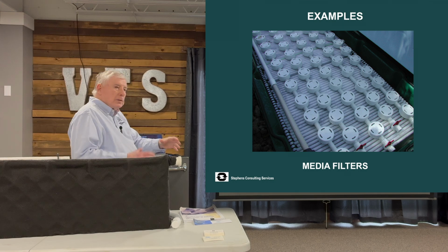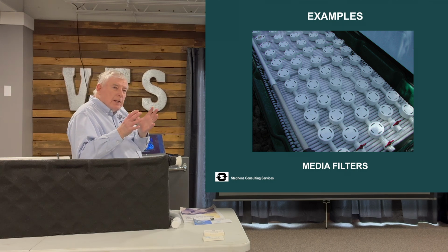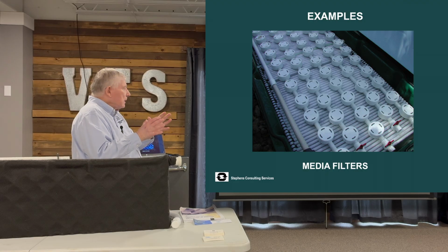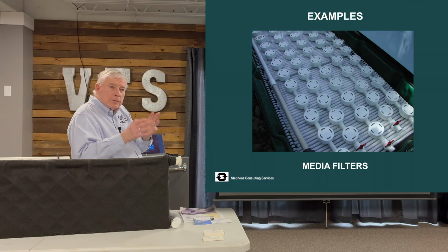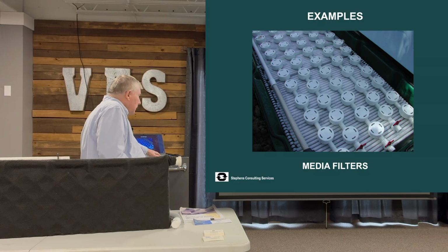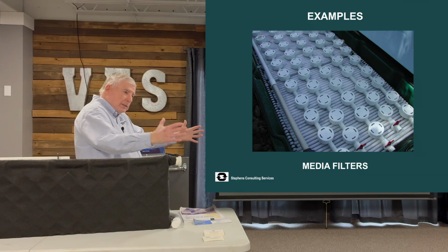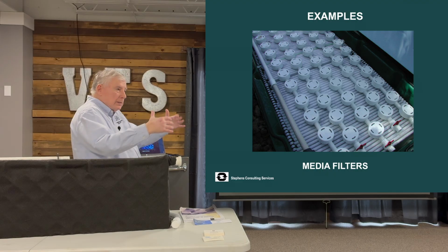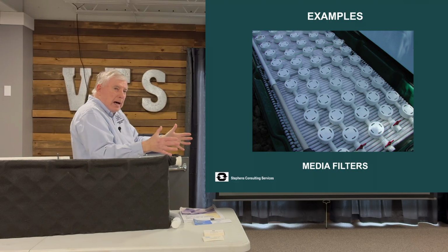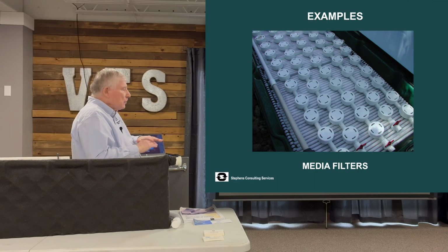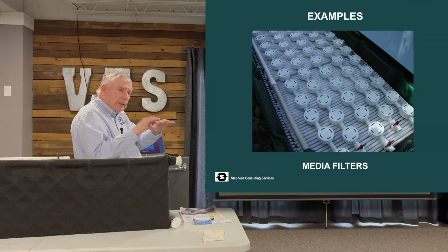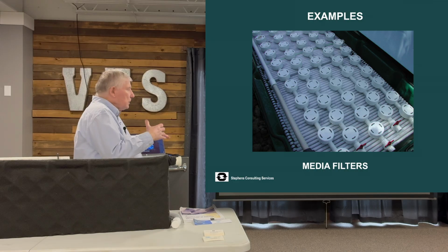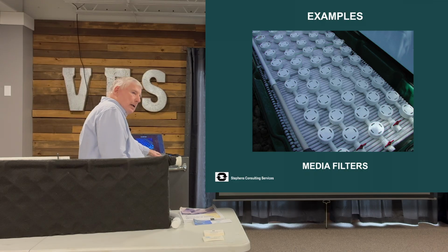That's pressure distribution to the nth degree because they've got an orifice about every 6 inches across the top of those filters. So that's how you shrink the size of the treatment unit down to a 3 by 7 or 8 foot pod is by distributing the wastewater equally over the entire system and using a media below that maintains aerobic conditions.